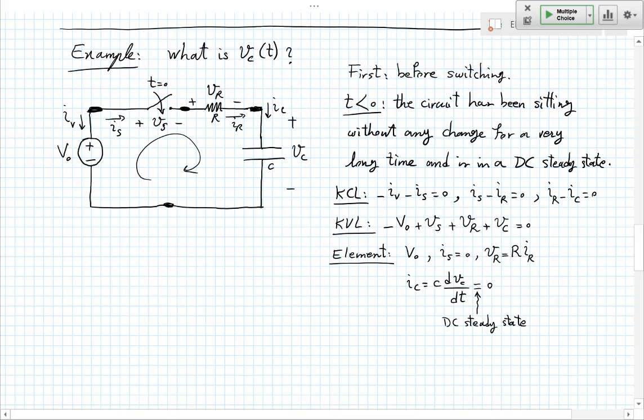But VC cannot be extracted from this. For this particular example, and this is not always the case, you actually need to know what the capacitor's charge was. Imagine you have built this circuit, you haven't closed the switch, you have connected things together. If that capacitor had one coulomb of charge accumulated in it 100 trillion years ago, it would still have it now, before the switching. Okay?